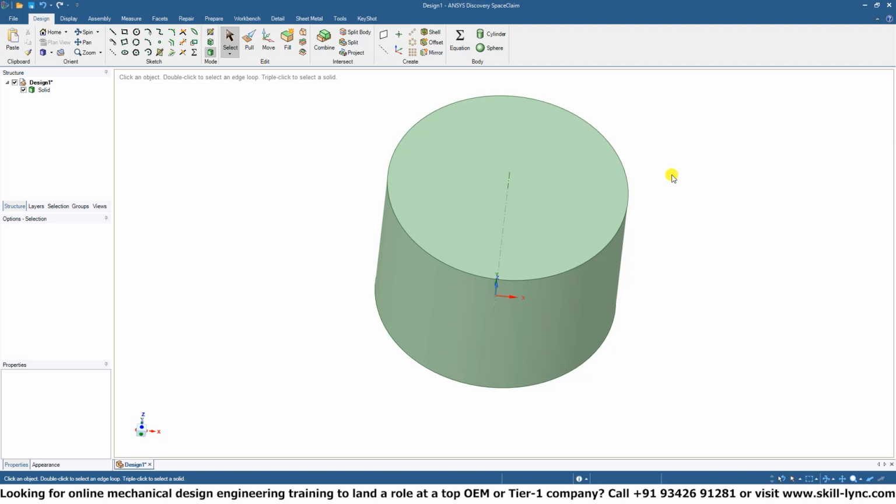So in this situation as well, when we want to cut a hole through this cylinder, we need to define a sketch and dimensions, or sort of a reference geometry, for the hole dimension and position that we would like to cut through the cylinder.